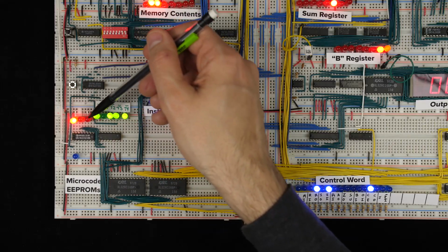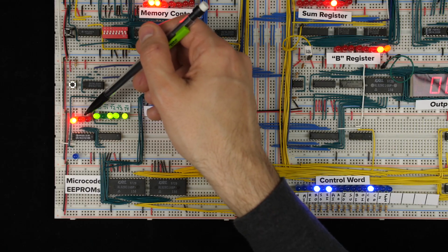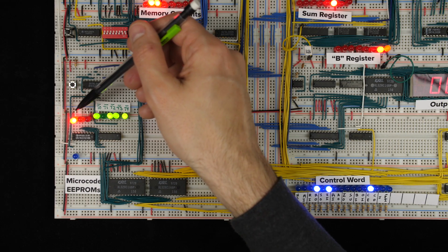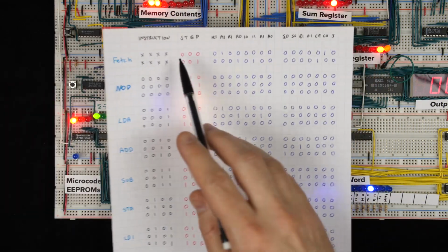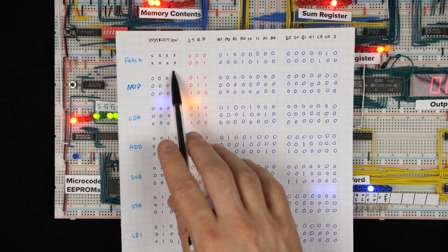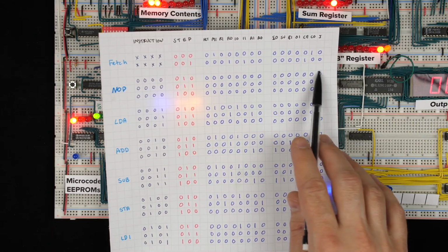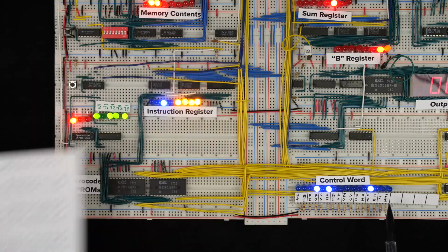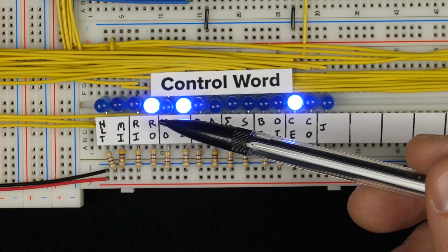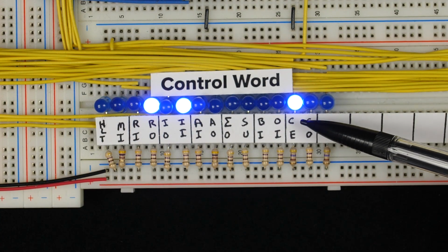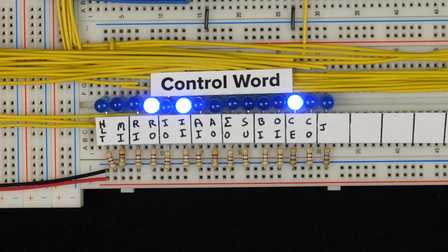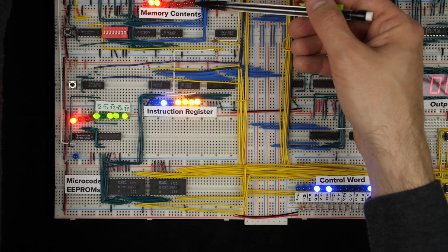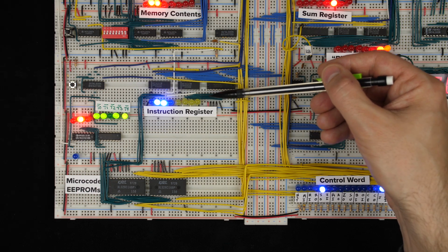So now we're at step 1, and these LEDs are turned around backwards. This is really step 1. For an input of step 1 with anything in the instruction register, the EPROMs are going to output this control word here, and that's what we see down here. This says RAM out, instruction register in, and counter enable, which increments the program counter. So with the next clock tick, the contents of RAM get moved into the instruction register, and we move on to step 2.